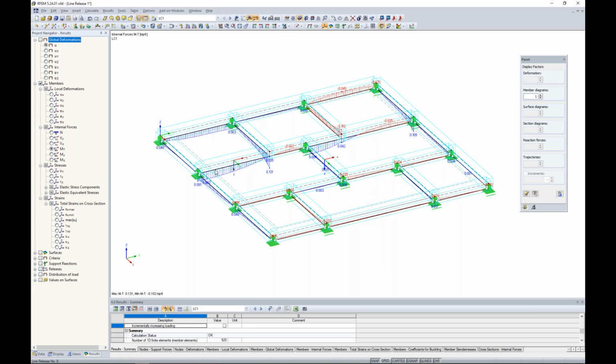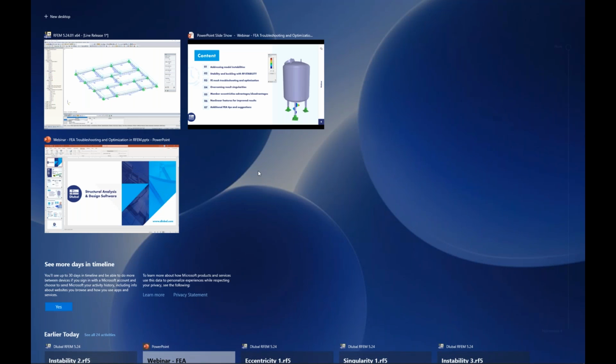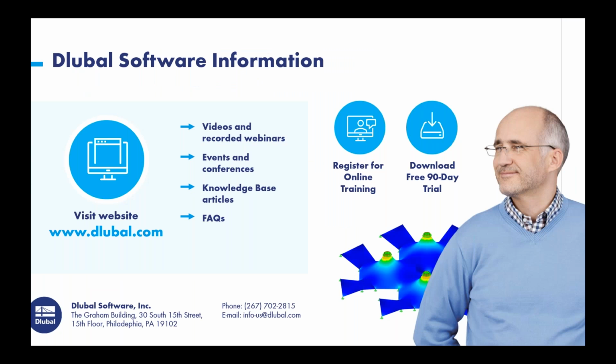If we take a look at our strong axis bending, we're no longer seeing those high peak negative bending forces either, which is exactly as you'd expect here. We have positive bending for all of our member elements. So some of these nonlinear applications can further be used in the program to really get the desired behavior that we want. Okay, so that will conclude all of our examples today.